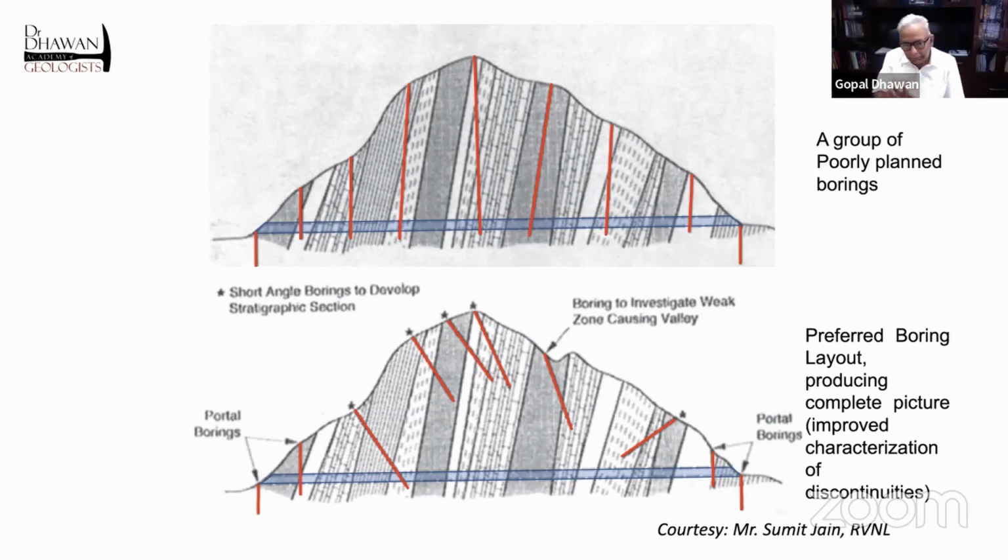So we have to consider geology before making the drilling program. And in the figure below, you will find that, respecting the knowledge of geology, these boreholes are inclined oblique to the geological formations.